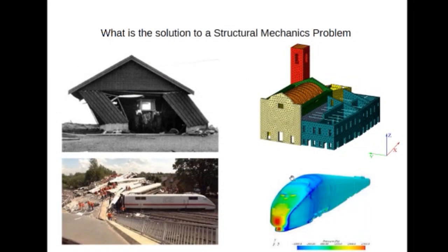To have a generic expression in terms of x or x squared or y squared and z to the power of some polynomial description over this whole train is going to be way too complicated. So what I'll show you as you go into this course is that instead of trying to solve this complex field in one go, with one function, we're going to break this up into small little triangles. Each triangle is a very simple field that we have to describe, because if you just look at the small patch there, the variation is quite trivial. And the variation around a small patch there is also quite trivial. And there as well, it's not that hectic. So then we have small little polynomial approximations. That's really what the finite element method is about.